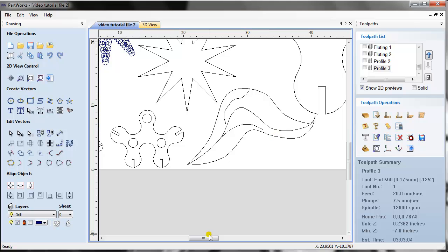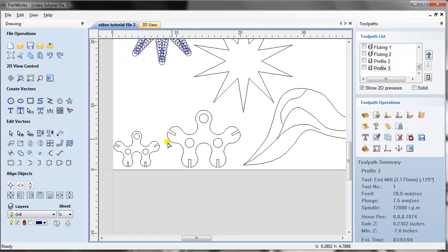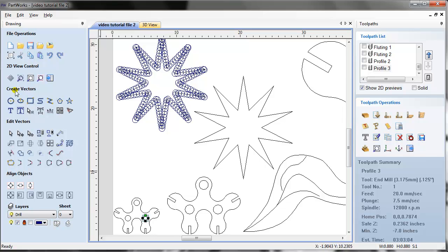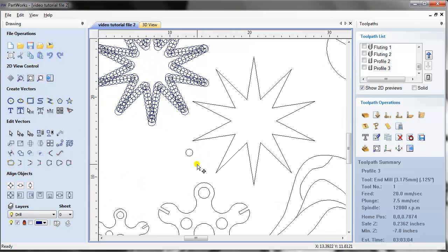Now there's one more wonderful tool to learn here. Say for example this is a circle and you want to copy it along the star the way I have done it here. You're not going to use Control-C and Control-V and make copies all around. There's a nice little button here, as you can see, copy object along the vectors. Both are vectors, so I would say copy vector along the vectors. All you need to do is hit that button.